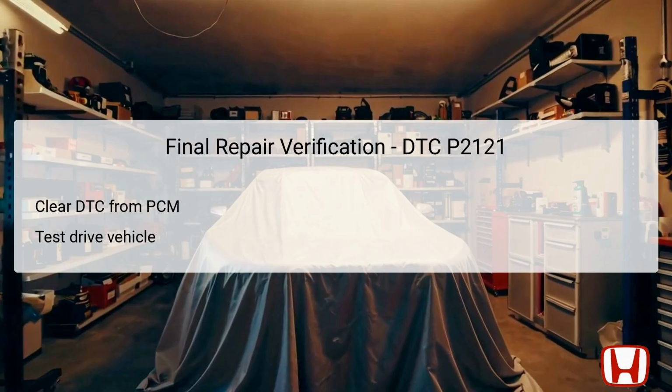Following this, conduct a test drive of the vehicle while paying attention to the accelerator response and ensuring that other warning indicators remain off. Confirm that vehicle performance has returned to normal and monitor for any reoccurrence of the DTC P2121 during your drive. Complete this verification process to ensure that all issues have been resolved satisfactorily, creating a safe operating environment for the driver.